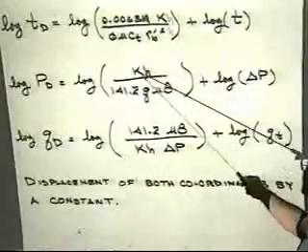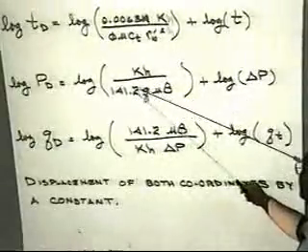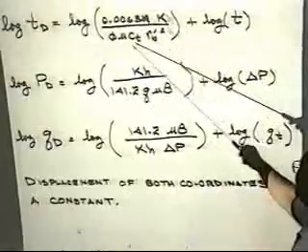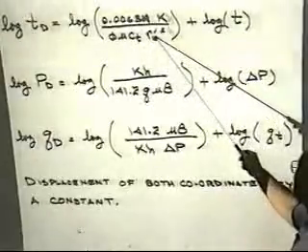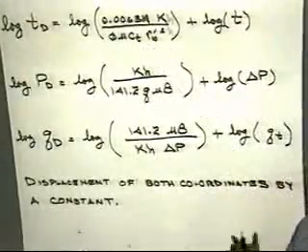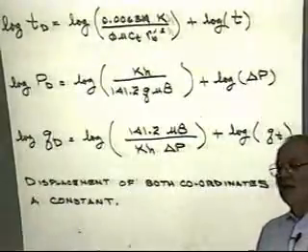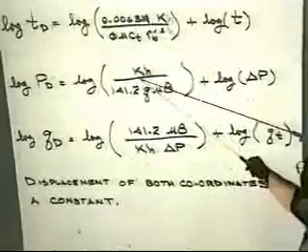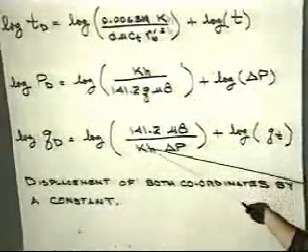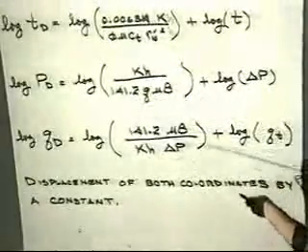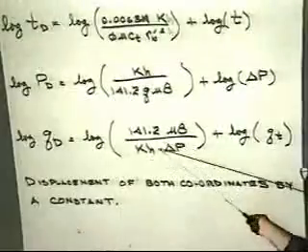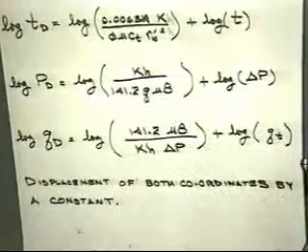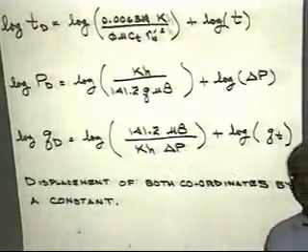These sets of variables here: the KH in PD, in mu beta, and in TD, the K, and the porosity, and the skin, and so on and so forth. This gets back to what we tried to show you before. QD is nothing more than the reciprocal of PD, but we substitute delta P instead of Q. So the form is identical.